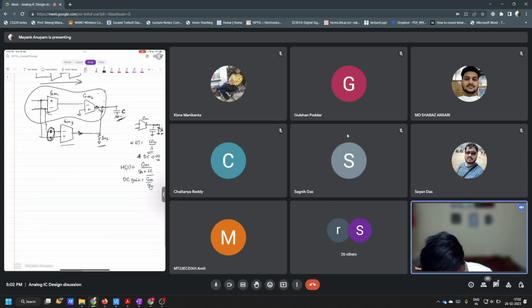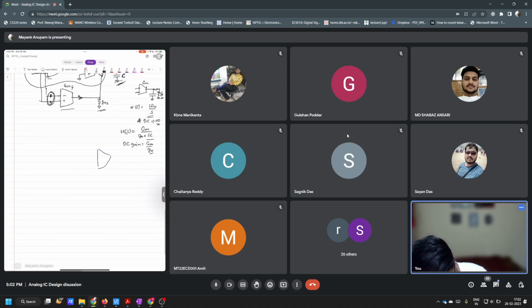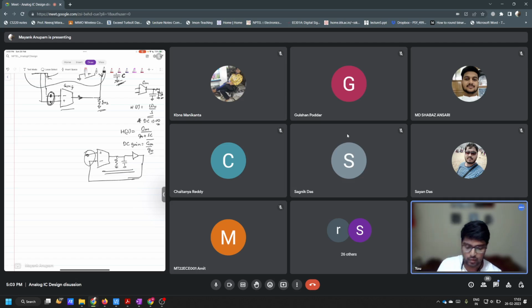Yes, sir. Correct. Now if this gain is not infinity, if you put this damped integrator in negative feedback around something, let's say this is a buffer. Okay, let's put it like this. If you put it in negative feedback like this, what will happen? Since the gain is not infinity, there will be some residual error, right? In between these two terminals. These two terminals should ideally, if this is Vref, then this should also be Vref, right? Ideally, if the DC gain is infinity.